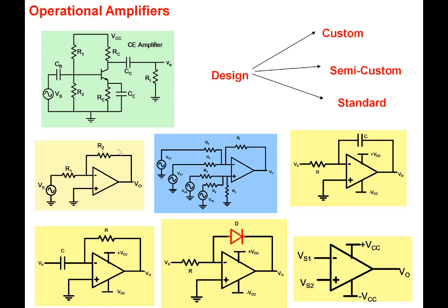It's customizable in the sense that you can take an op-amp. It has a very simple interface, and you can customize it. So in fact, anybody can take it. A material scientist or whoever can take an op-amp, and what they can do is add an R1 and R2, and the ratio decides the gain of the amplifier. Anybody can build an amplifier. A 10th class student can build an amplifier now. But inside this op-amp is a very sophisticated circuit, with a very simple interface. And you can customize it. So this is the important point that one can illustrate through the op-amp here, the customizability, that semi-custom design.